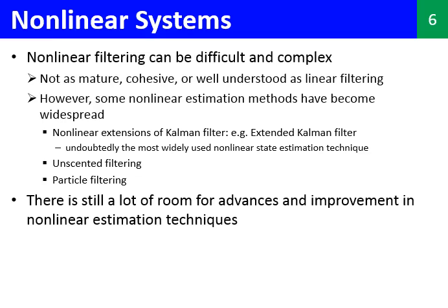An example would be the extended Kalman filter, which is undoubtedly the most widely used nonlinear state estimator. The second approach is called the Monte Carlo approach, where the problem is addressed using numerical simulations. The particle filter is a very good example of a Monte Carlo estimator, which we will discuss later. So there is still a lot of room for advances and improvement in nonlinear estimation techniques.